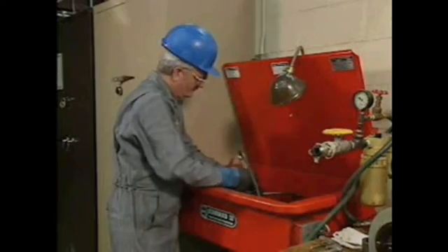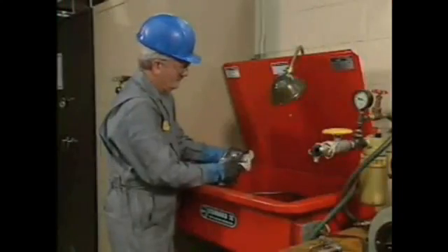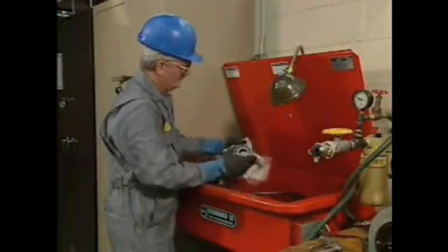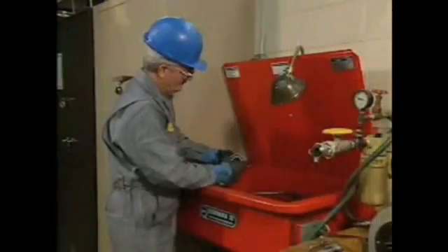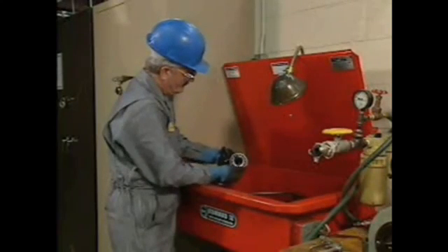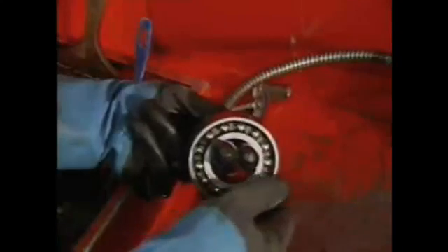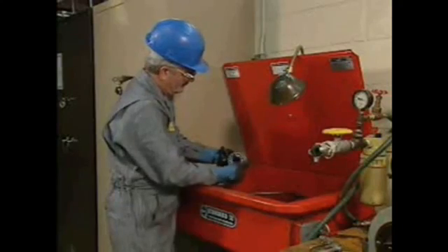After the failed bearing has been removed from a shaft, the mechanic cleans the bearing with an approved solvent to remove grease and dirt. Then, after the bearing has dried, he inspects the rings and rolling elements. He turns the bearing slowly to determine whether there is any stiffness or binding when the rolling elements turn. He also checks for signs of failure such as spalling, burn marks, cracks, dents, and pits.